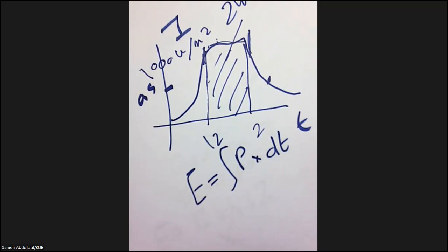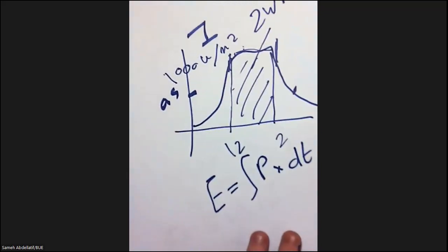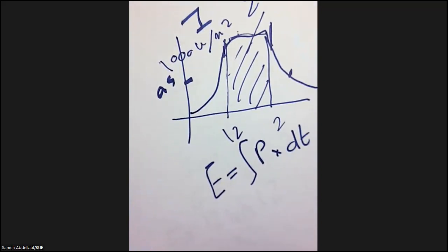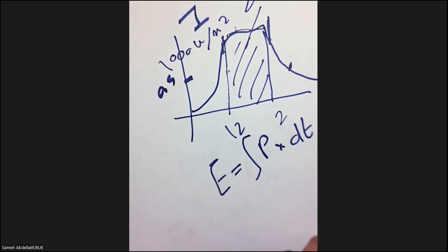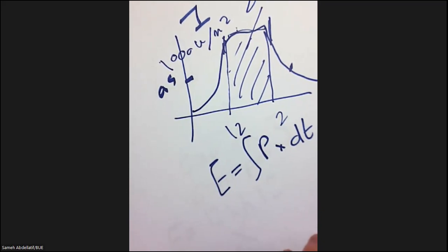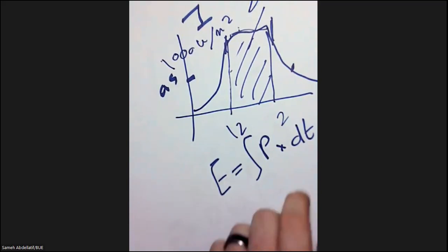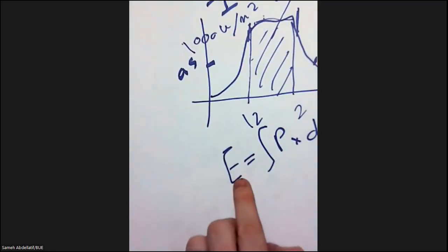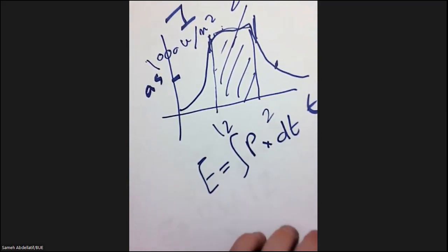That means to calculate the energy produced by this small 1 watt PV module, you have to have a big data set of information related to different locations and different days of the year. So you can say, okay, today is the 1st of October, we are located in Cairo. Then we go to our database, get the curve of the 1st of October in Cairo, and calculate the area under the curve to know the total energy. As you can see, it is a very sophisticated process to calculate the energy per day.